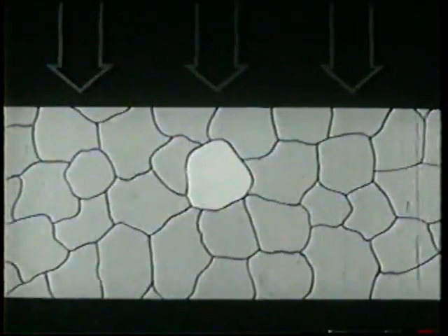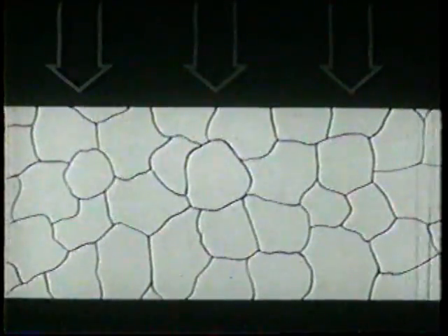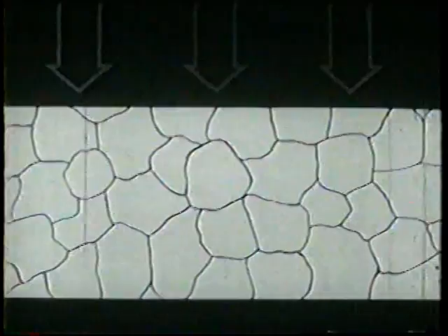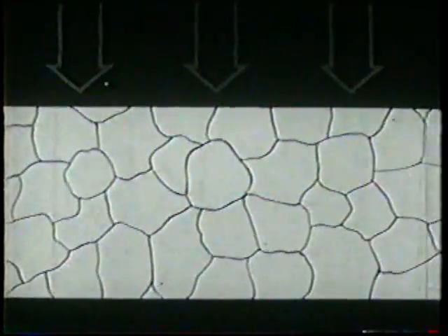The deformation and rotation of any one grain is restricted by the differently oriented grains adjacent to it. These may also be rotating. Consequently, there is movement along the boundaries as well as along the slip planes. Each grain is now rotating, moving along its active slip planes toward the axis of tension or away from the axis of compression.